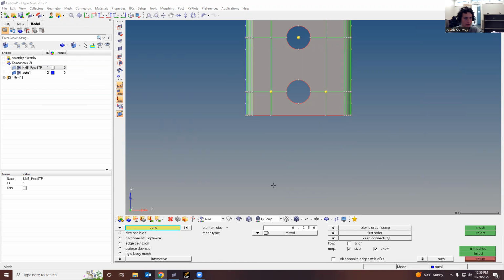So yeah, I did get this to work fairly well with a 0.5. A 0.1 will definitely work. Again, it will be computationally expensive, so I kind of want to find that middle ground. So I'm going to just do 0.25 because theoretically, if I only had 4 sides using a 0.5 mesh, then I should be able to get about 8 if I halve the size of the mesh.